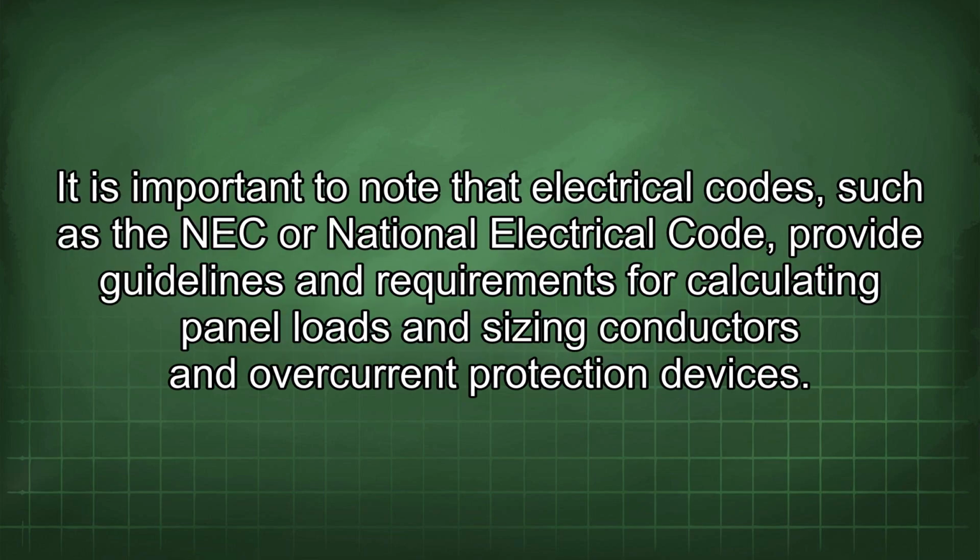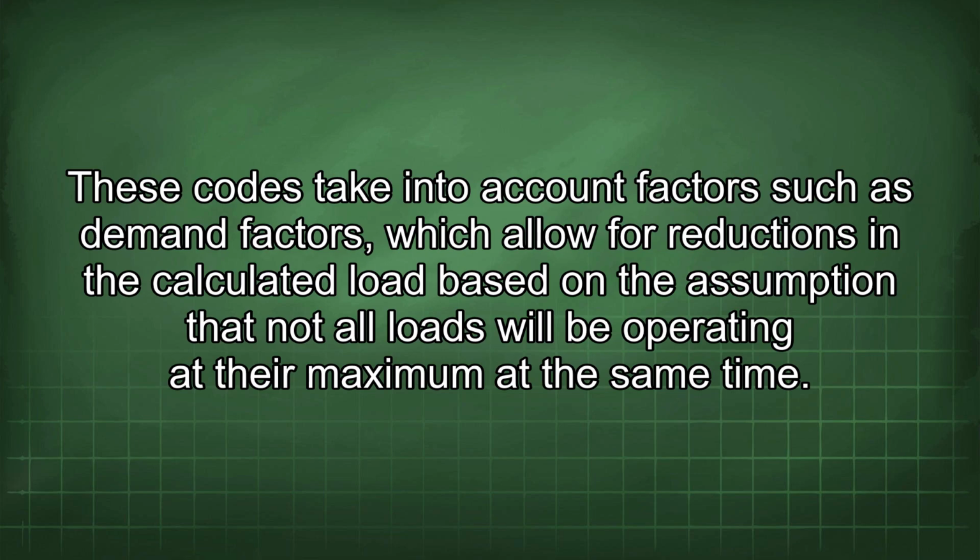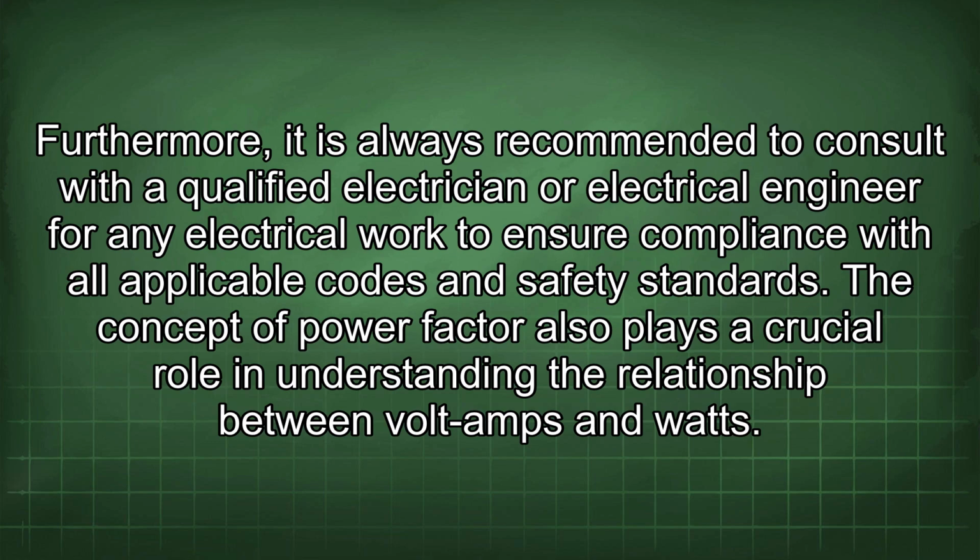It is important to note that electrical codes such as the NEC, or National Electrical Code, provide guidelines and requirements for calculating panel loads and sizing conductors and overcurrent protection devices. These codes take into account factors such as demand factors, which allow for reductions in the calculated load based on the assumption that not all loads will be operating at their maximum at the same time. Furthermore, it is always recommended to consult with a qualified electrician or electrical engineer for any electrical work to ensure compliance with all applicable codes and safety standards.